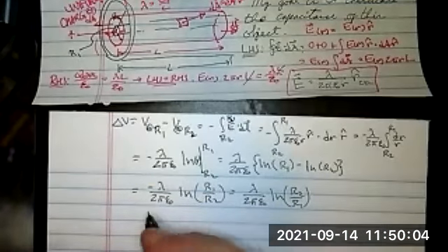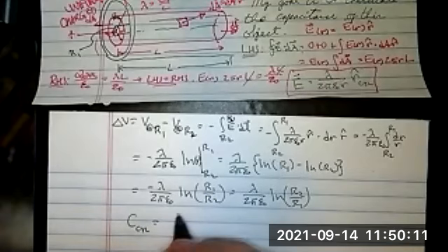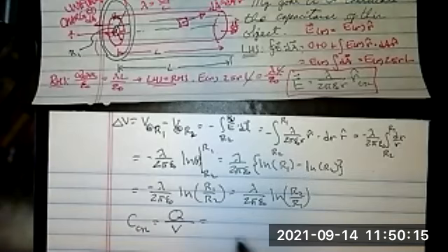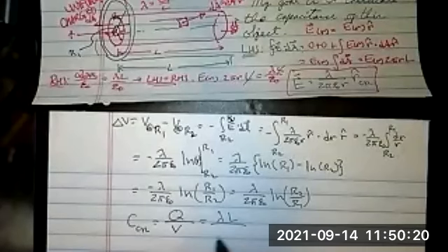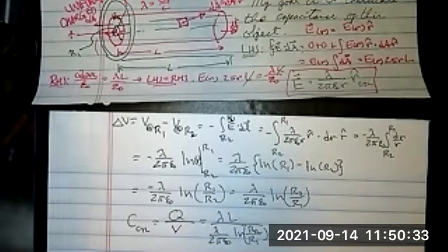So now that I have that, I'm in a perfect spot to calculate the capacitance, and the capacitance of the cylindrical object is Q over V. Well, the Q is lambda times L. And then the V, of course, is lambda over 2 pi epsilon naught ln R2 over R1, which again, notice the charge related quantity cancels out.